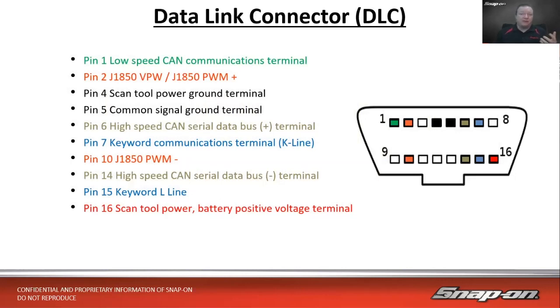Well, many of them, at least with the communication with the scan tool type networks we're talking about, the easiest place to access that is at the diagnostic connector underneath the dash, right? And we talked about what all the wires were there. The key components we want to talk about tonight are going to be our grounds, right? So pins 4 and 5 are ground. Pin 16 is always power, as long as the fuse is good, right? So 4, 5, and 16.